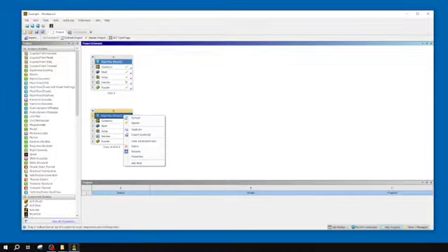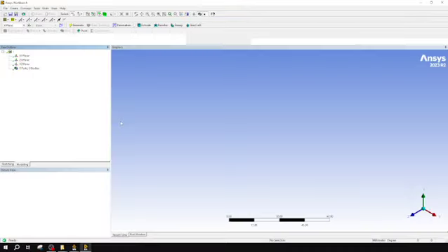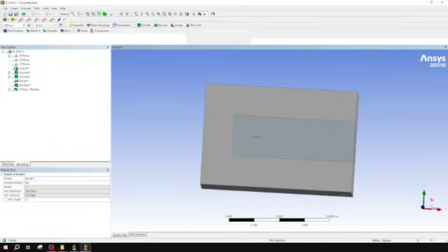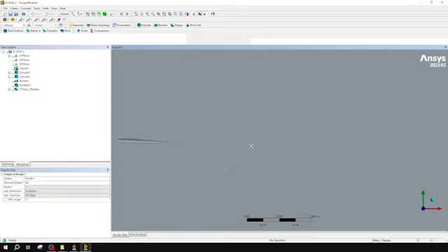I'm going to rename this to AOA 2. Angle of attack is what AOA stands for. Going to go into my geometry tab, and then I'm going to go to this rotate. I'm going to rotate it by 2 degrees. Enter and generate. You should be able to see just a slight angle on that. So now I'm good to close this.